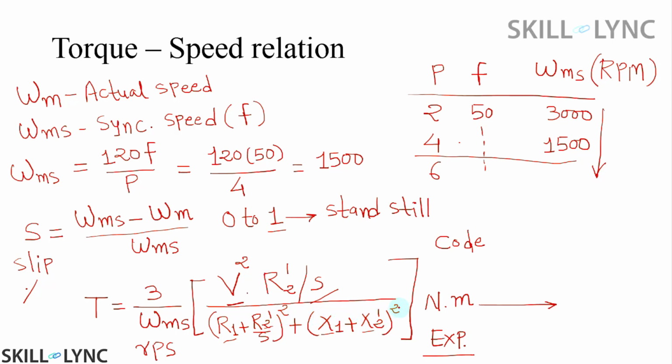Sometimes they may be given by the manufacturer, or if you have a motor and you do the no load and block rotor test on this motor, you can derive these parameters. What is a no load and block rotor test? In the no load test you connect nothing on the motor shaft and you observe the power, and you can calculate some of the parameters from this, and with the block rotor analysis you calculate the other parameters.